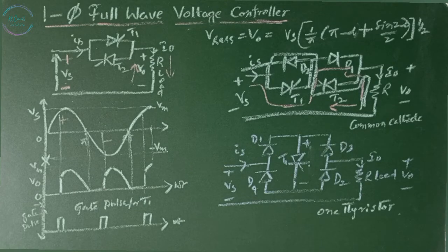However, if there is a large inductance in the circuit, thyristor T1 may not be turned off in every half cycle of the input voltage, and this may result in loss of control. It would require detecting the zero crossing of the load current in order to guarantee turn off of the conducting thyristor before firing the next one.